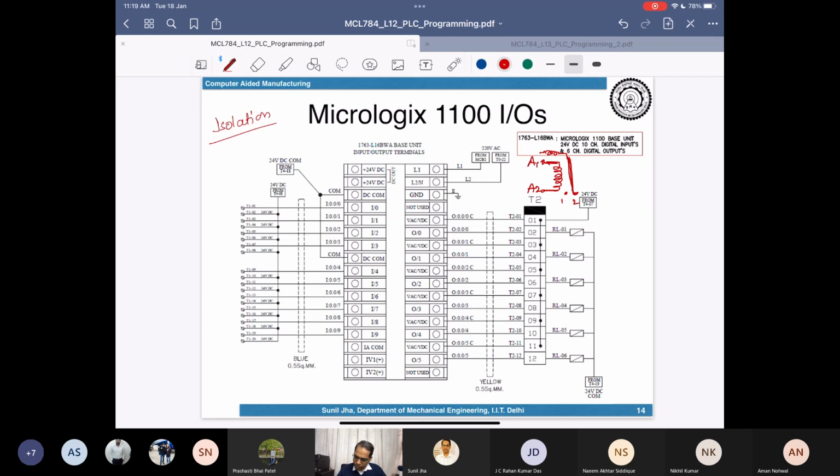So if you see here, I will be adding a wire here. This is one wire which is common. And then you will be having 2 more wires here, 1 and 2 like this. This is known as normally closed, and this is known as normally open. So these 3 are the electrical terminals on this relay. So this relay has electrical terminals, and then these coil terminals over here, A1 and A2. So these 3 contacts are there, and A1, A2 are the coil here.